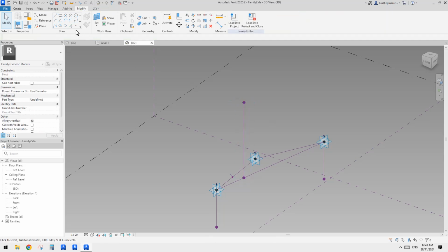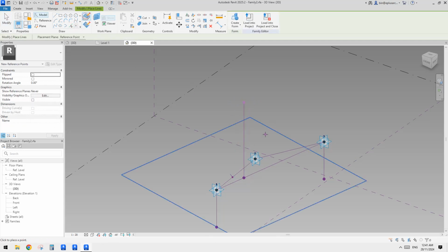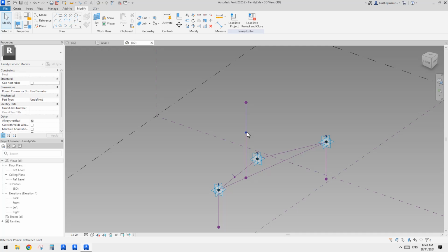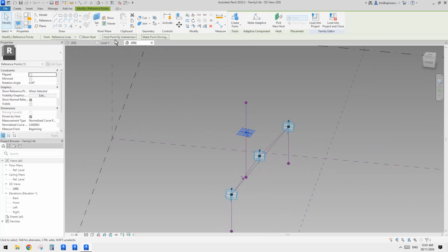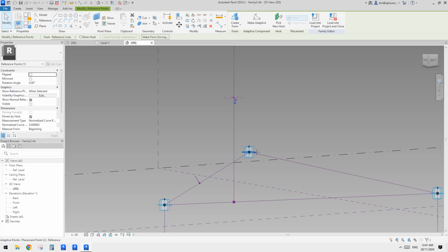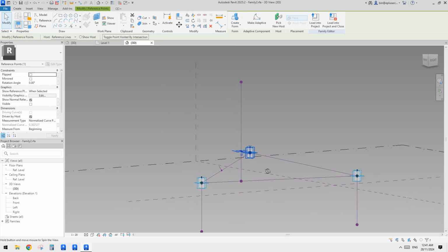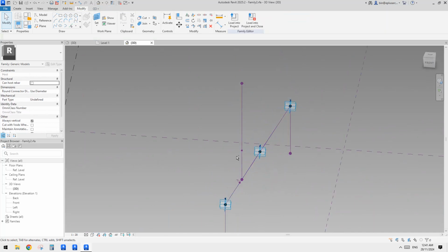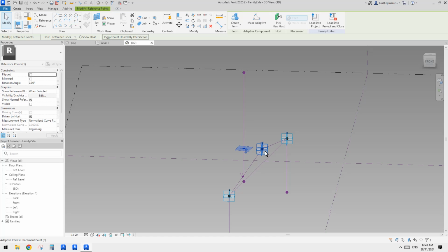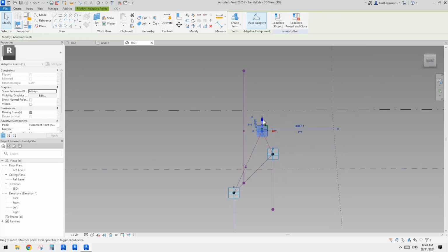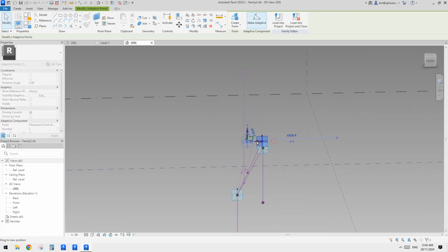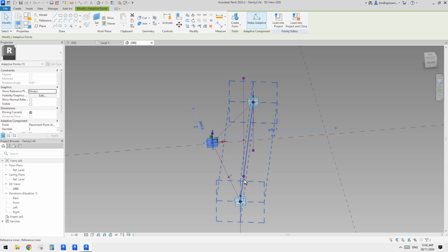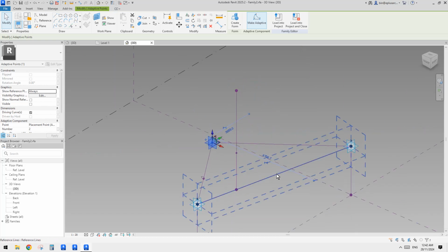Okay, and then place a point, use draw on face onto this reference line, and select this point, and once again we're going to use host point by intersection. So this time pick the horizontal world plane of this point too. So now we have this point that always matches the height of point 2, and it always sits above the reference line between point 1 and 3.